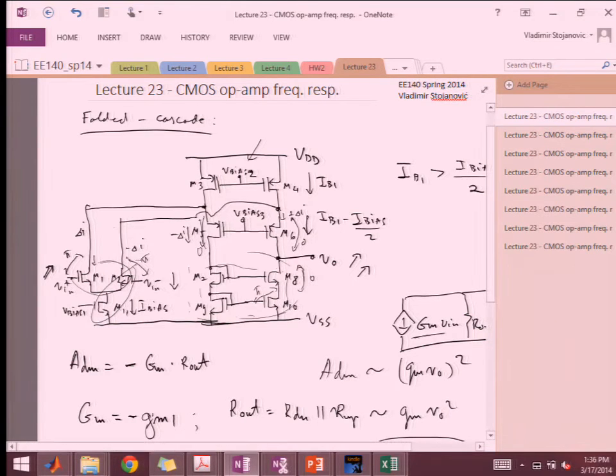You know, if I want to maximize the swing at the output, what should I set my V bias 2 to be? In what exact condition should I keep these two transistors so that I kind of maximize my output swing? What should be the VDS of this M4? It's a current source, right? So how do we set our current sources, the output? What's the minimum a current source needs across drain source to stay in saturation? I'm hearing VTH, something else. What was something else? VOV, okay.